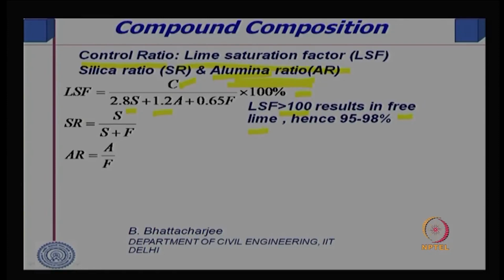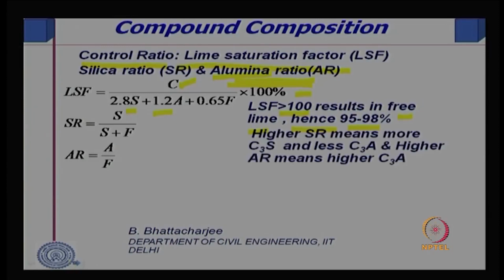So, they will remain unreacted. Therefore, the proportion of the various oxides is very, very important. Generally, lime saturation factor is maintained at 95 to 98%.